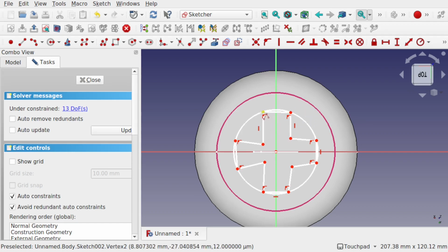You probably already know this, but the constraints, let's hit escape to get the mouse pointer back. If I wanted to constrain all of these, I've got multiple horizontal lines here. So there's 2 ways of doing this, like clicking all the horizontal ones and adding a horizontal constraint in there, or clicking the horizontal constraint first and then selecting the lines one by one, because we've still got the tool active. And vertical constraints, which are these, this one and this one.